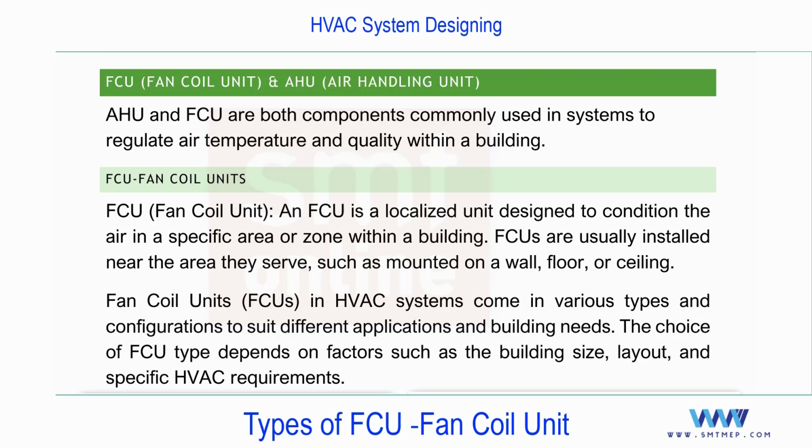You see, this FCU and AHU is an air side unit, and this is common for split. I'm not talking about both, just in general at this level. After learning this, you'll get a clear idea. So if you talk about FCU and AHU, you'll find them in a split system, ductable split, VRF, and the chilled water system. District cooling is also a chilled water system, but for a community, so this is applicable there too. And if you talk about geothermal, in that case also you'll find this unit. So this unit is common in almost all systems.